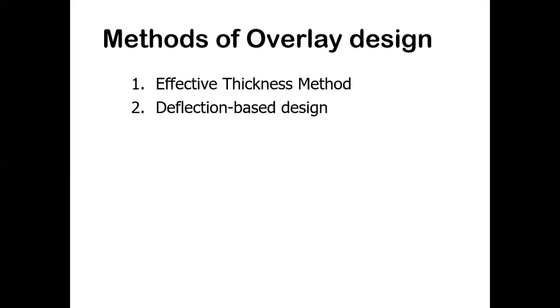To cater for that, the other approach of overlay design is the deflection based design. Now, what we do is use some standard equipment, which has also been standardized as a standard test, like the Benkelman beam and falling weight deflectometer.